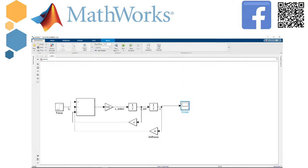So what can I do? I can just connect the scope with the force, double click on the signal of the force and call it force, external force maybe. And more than that, I can just set a stop time of, I don't know, maybe 25.